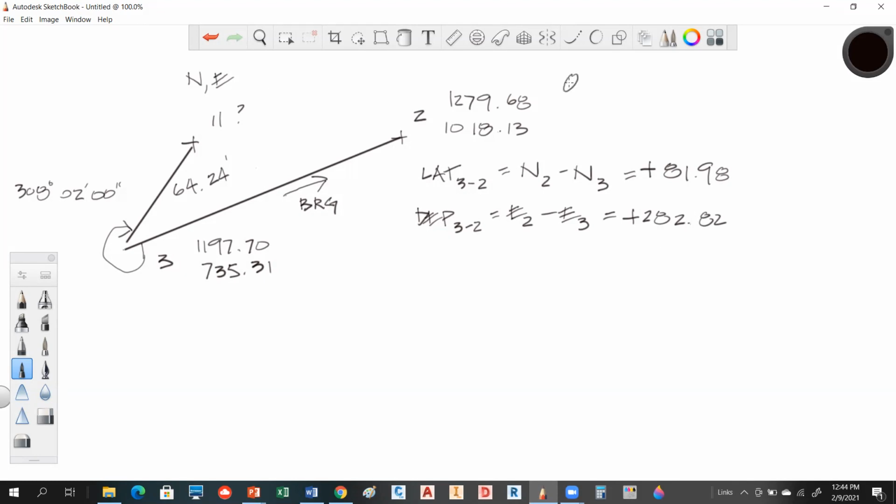So the bearing then is the arctangent of what over what? Departure over latitude. Right, and that's always departure over latitude, right? We never flip those. If you flip them, you will get the answer off of east, and that wouldn't be a bearing. So I'm going to go ahead and, again, watch me so I don't transpose anything.